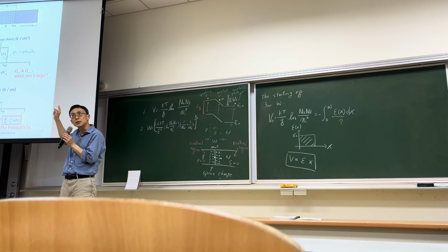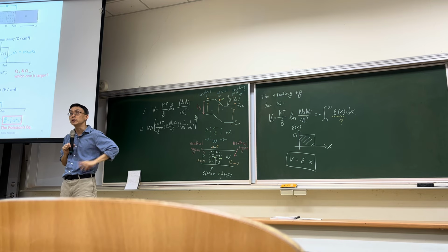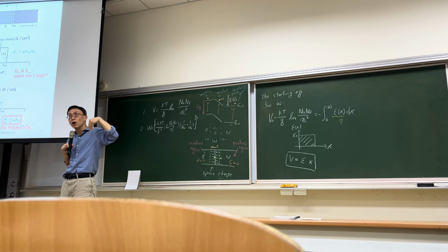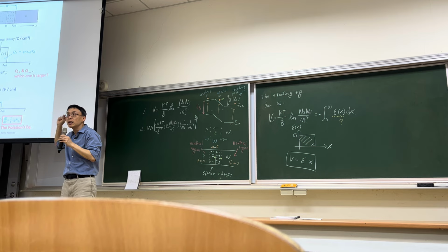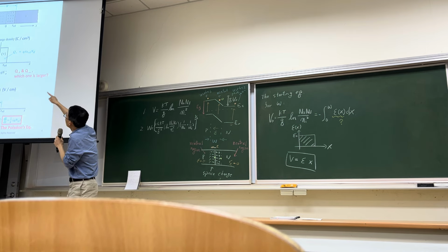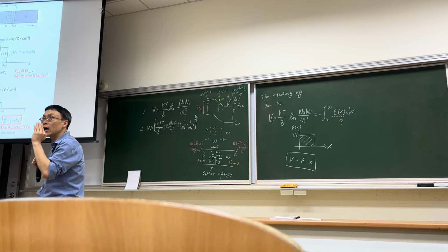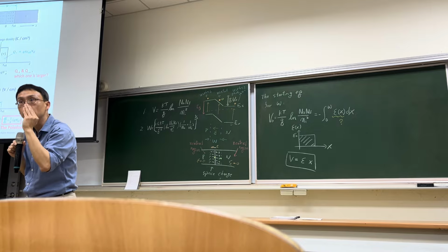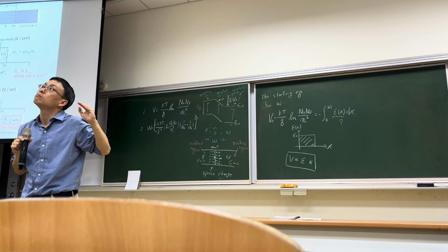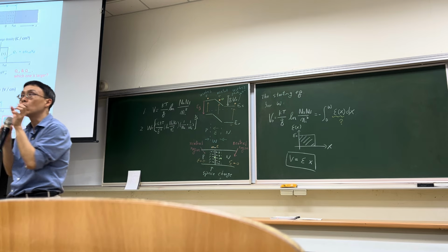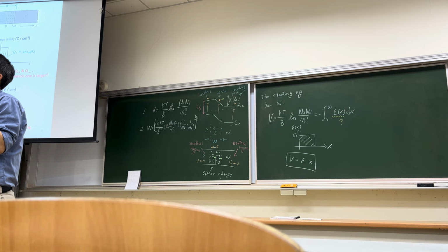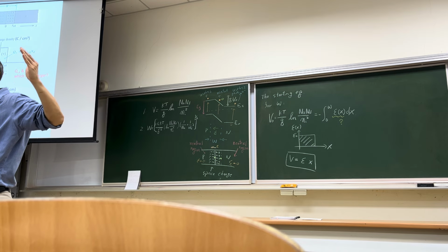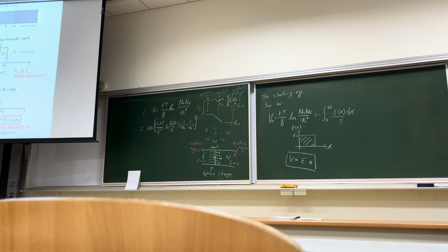And in this figure, we intentionally make the doping concentration not the same, which means one side is of higher doping, the other side is of lower doping. In this example, you can see we have more N-type doping than P-type doping. So we don't have an equal distance of the space charge. One is wider, one is narrow, right?